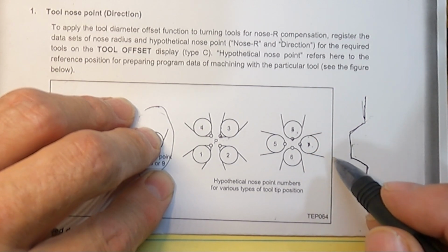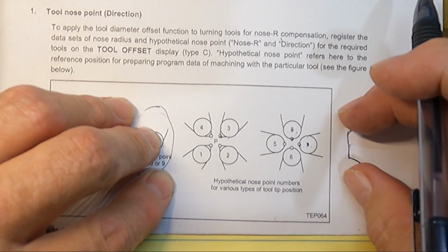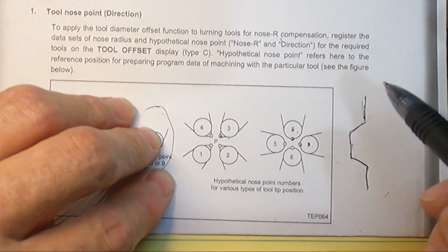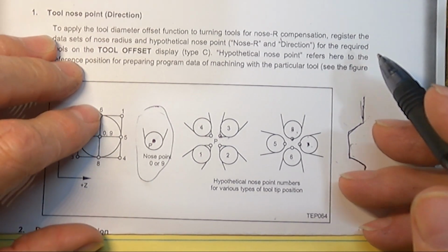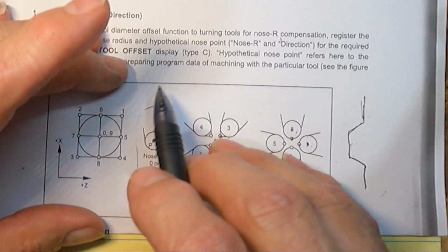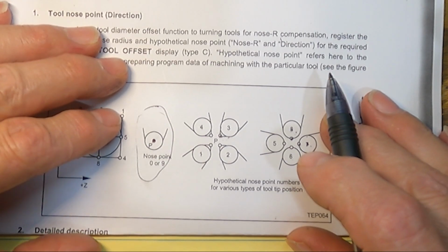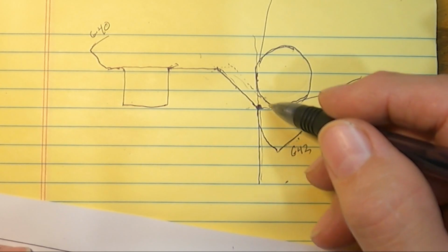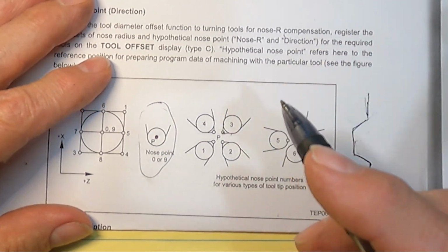Most of these tools that are made for these directions, you can kind of touch the tool off out here somewhere, and you know the width of the shank, and you can set it half the width of the shank. That's the way I've done it before. If that's accurate, you'd have to check on your shank if that's accurate. So these are the numbers you set in your offset page if you're using tip radius compensation. And I've kind of explained a little bit about why you do it and why we used to use it for manual programming a lot in the old days before CAM software.